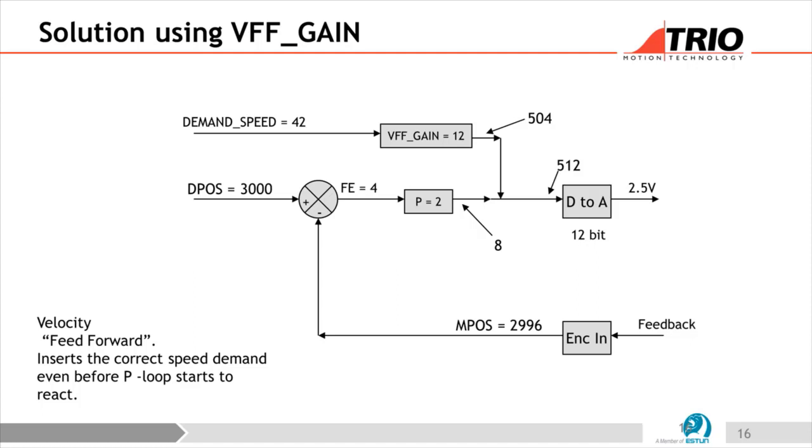And if it was easy, or even if it was not easy, but quite doable, we would have done it by now. But it is a very tricky thing. Just to recap very quickly, if you use velocity feed forwards, you don't need I and D. You just need an arbitrary proportional gain. Well, I've never fully appreciated that. You say arbitrary. Yeah, it should be a reasonably thought out proportional gain. Right. You don't need the I and the D, because the VFF gain will take care of it.